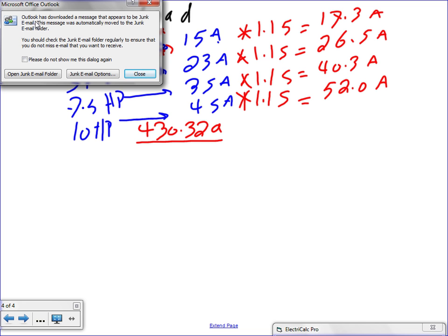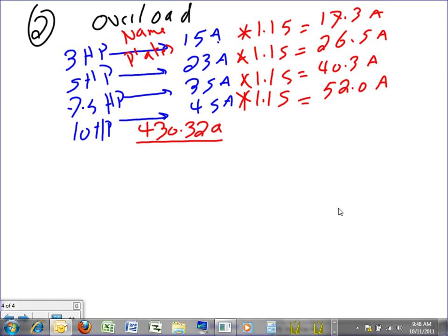So if you can't get 17.3, you have to get lower than 17.3, like 17. So we don't go up or down. If we can't get an exact number, go down. There's no standard numbers, my point is. Are these also called the heaters? They're also called heaters. Now, if you have an electronic overload like this, it's easy because you can adjust them. If you have a heater, then you have to go to the manufacturer and buy the closest heater that you can get. So if you can't get 17.3 amps, which I doubt that you will, you're going to get a 17 amp heater. Go low.